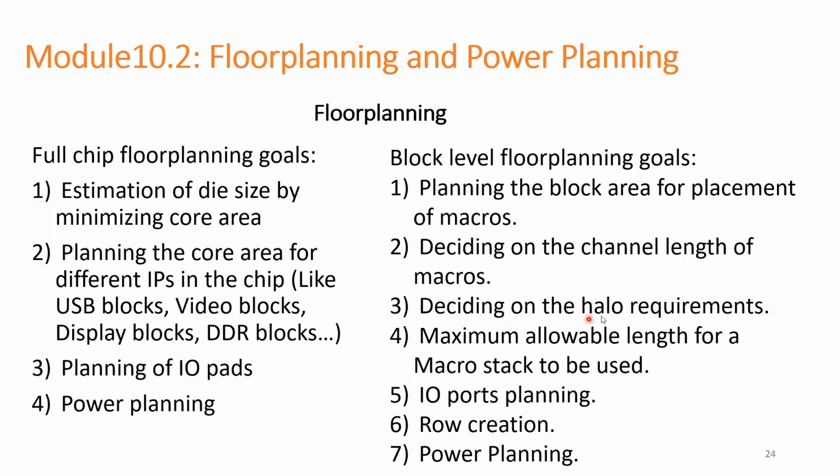Next, deciding on the halo requirement. Halo means we create a hard keepout blockage around the macros to avoid standard cell placement near the notches or near the pins of the macro. If we allow the standard cells to sit near the pins, that will create congestion and maybe other timing violations. If we create the halo, the tool will completely block the placement of standard cells near the macros.